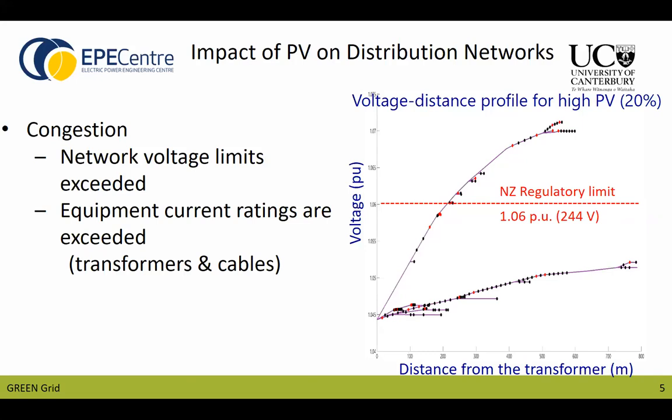Now, if we just turn to EVs, EVs is similar yet opposite. So I think electricity distributors are more used to the loads and the voltages dropping. So if you have a whole lot of EVs charging, we'll neglect thinking about vehicle to grid at the moment, what we're seeing is that the voltages can drop quite sharply. And so if you put it all together, it doesn't actually cancel out, unfortunately, because the times when we've got high generation do not usually coincide with high loads. So actually what distribution businesses are worried about is these extremes, so the very high voltages and the very low, so you're getting an increase in spread.